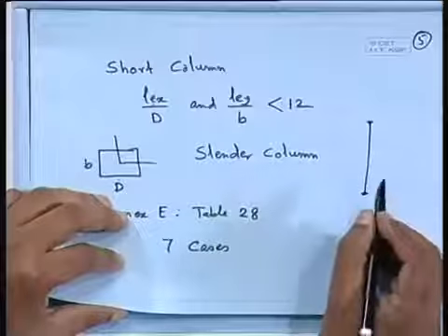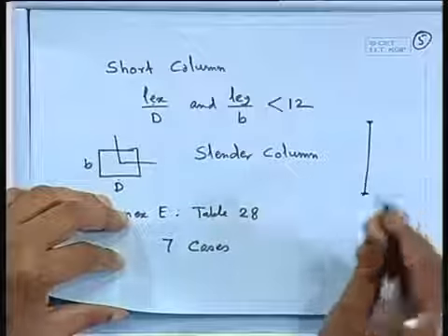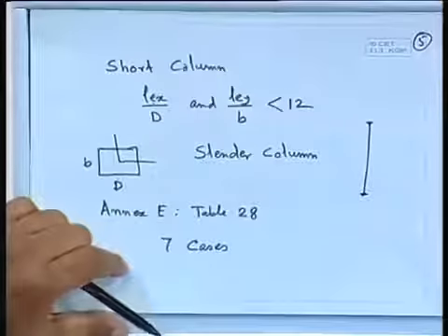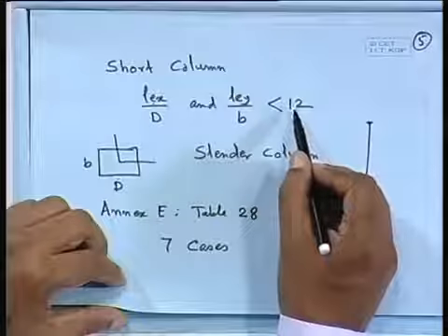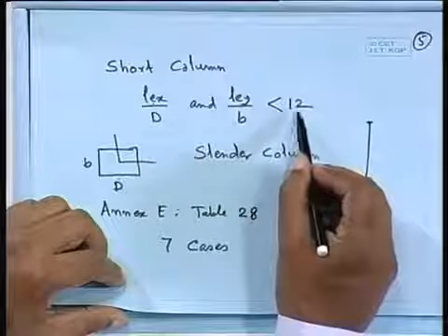In a few cases, possibly in our institute, those front columns, if you get the dimension, you will find out they are long columns. Similarly in other cases, if you need a big headway, possibly for a truck or other loading and unloading, there you have to make it a long column, because there is no other way. So that's why we do it. It is not always possible to make it a short column, but mainly for buildings and others we always provide short columns.